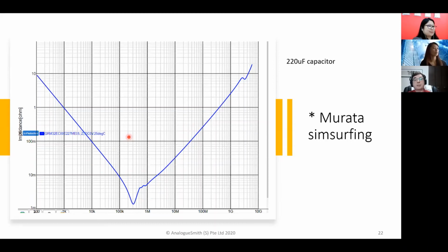And so in this case, you're not going to be working with a capacitor much beyond 100 kilohertz, okay? Its impedance is very low. So if you just need a very low impedance, I mean, we've got 1 ohm here, even as we're getting up to a gigahertz, right? Then it will still look like a low impedance, but it's not a capacitor at these frequencies, it's an inductor.